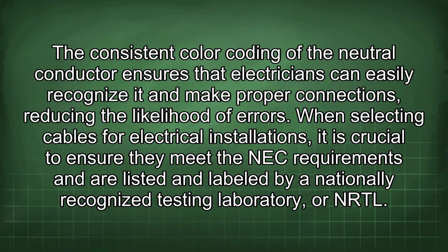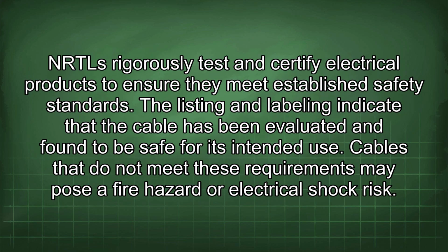When selecting cables for electrical installations, it is crucial to ensure they meet the NEC requirements and are listed and labeled by a nationally recognized testing laboratory, or NRTL. NRTLs rigorously test and certify electrical products to ensure they meet established safety standards. The listing and labeling indicate that the cable has been evaluated and found to be safe for its intended use. Cables that do not meet these requirements may pose a fire hazard or electrical shock risk.